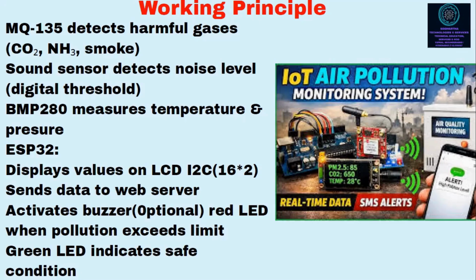Then this sends data to the web server also, because since it is an IoT project, web servers have been added. And the final part is the output. You can use a buzzer and LEDs. I have used two colors here, red and green. Red will indicate that the threshold level is very high, that is, the sound or any other pollution is more than the given values. Green is the safer side. So this is the project.